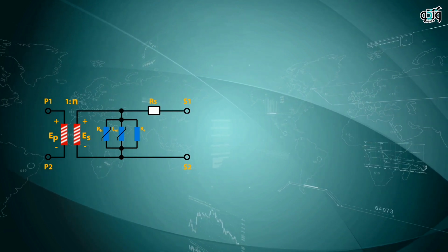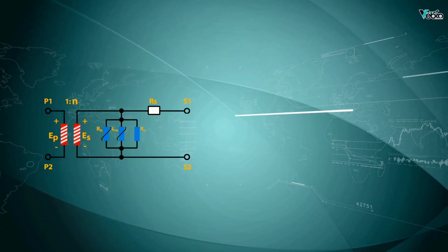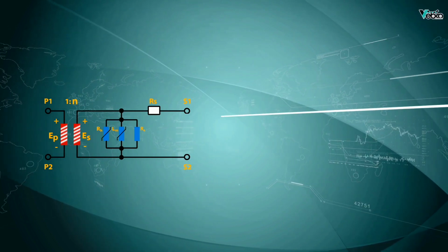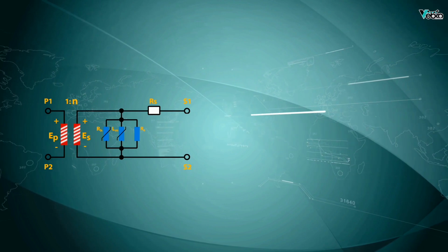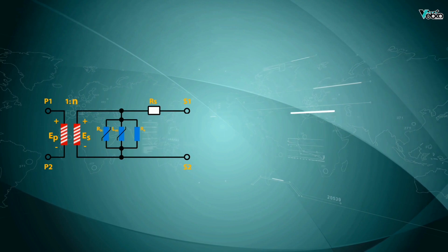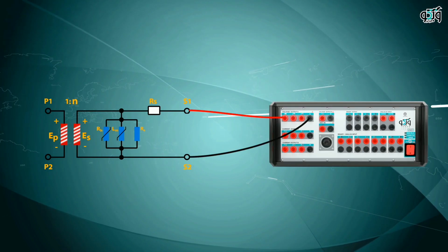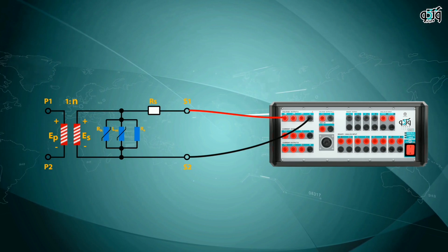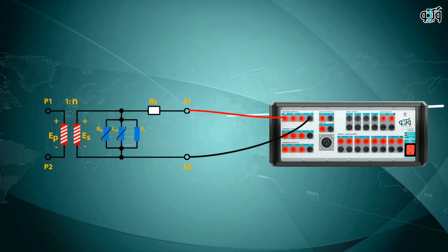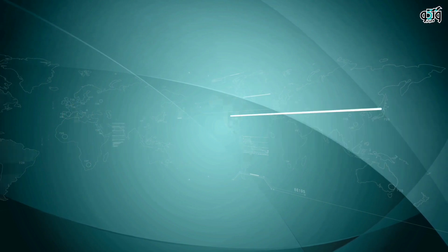Rs indicates the resistance of the CT. In the parallel branch, Rad and Rh stand for the Foucault and hysteresis losses of the core, and L stands for the magnetizing inductance of the CT secondary. To perform the excitation test, the secondary of the CT is fed by voltage and checked to see what nonlinear element is causing the CT to show a nonlinear behavior even in lower voltages.